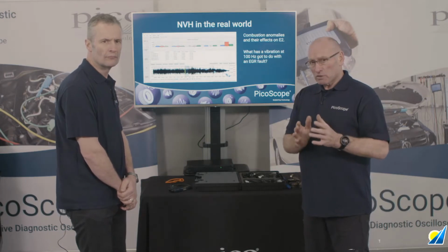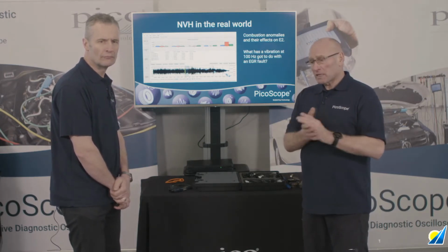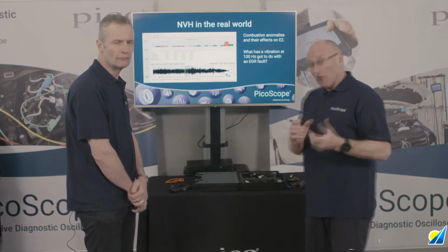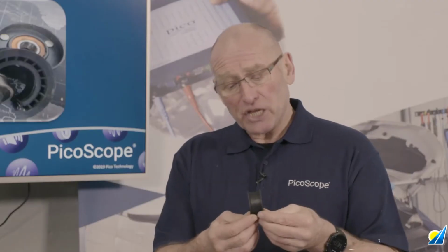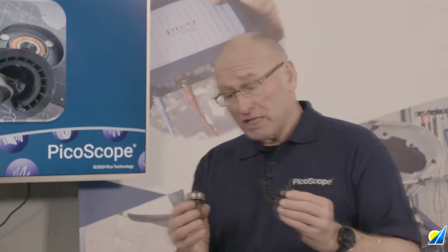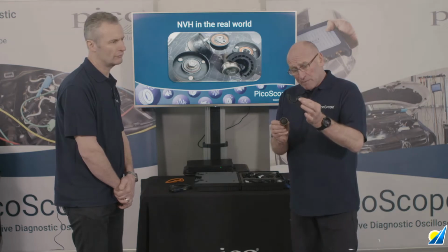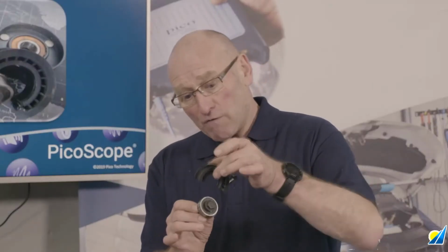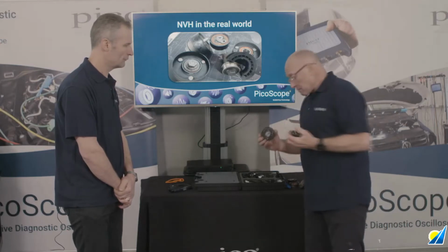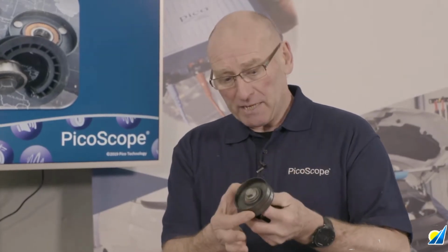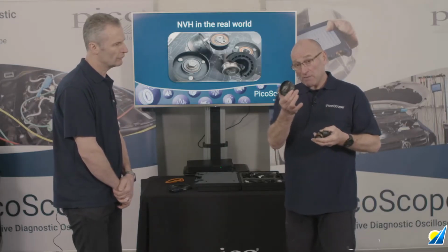And to be honest, what I found really shook the foundations of my belief, because it was a critical fault whereby the timing belt guide had separated from the pulley. So the pulley is here. This guide had actually separated and, for want of a better word, was hovering in no man's land within the belt chamber. Additionally, we did find an excessive bearing noise from the serpentine belt guide. So that certainly was adding to some of the vibration and noise.